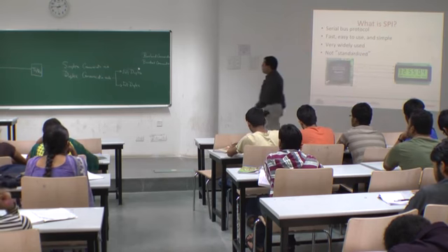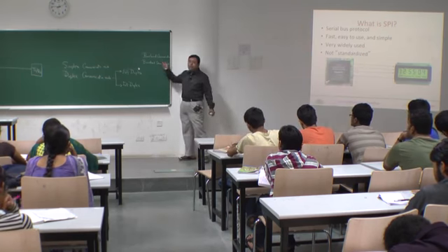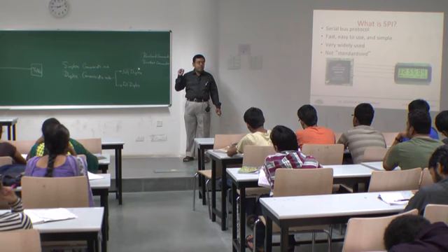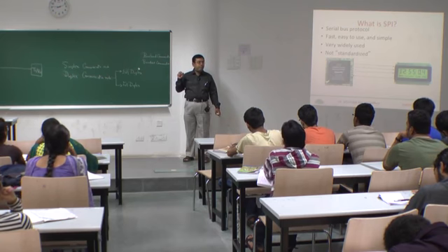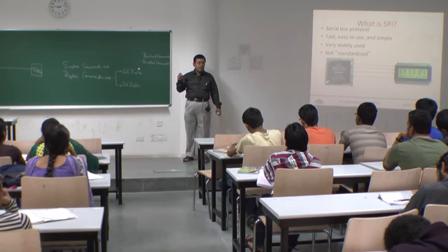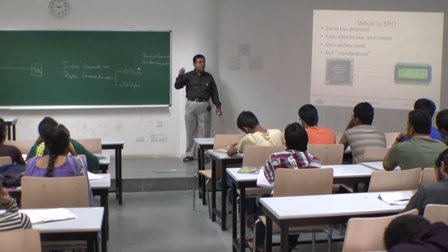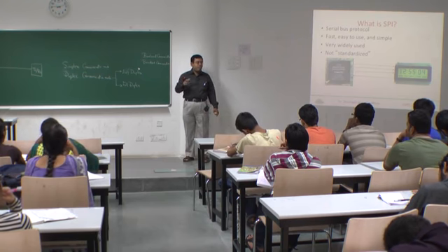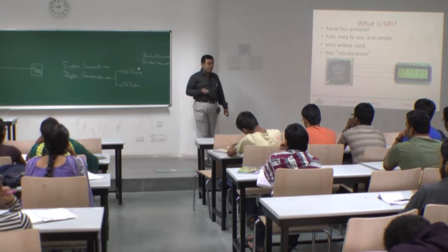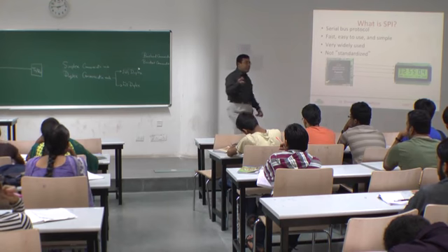So, but then if you want to transmit data from different channels over the single communication channel, then you have to multiplex the data coming from multiple channels and allocate individual time slots to individual input channels by time division multiplexing, right. So, what is this time division multiplexing?